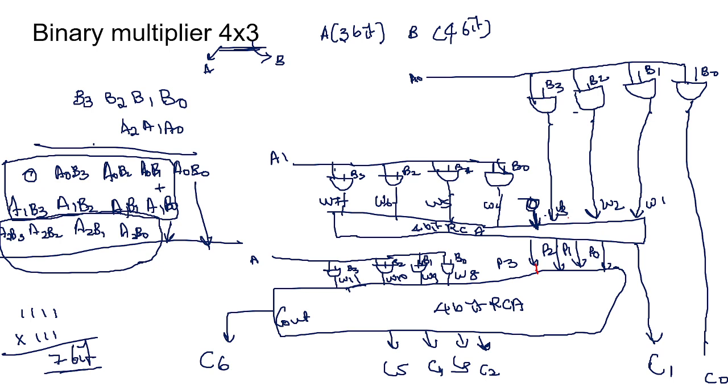So all this W will be wires, and the AND gate terms, the product terms, I am mentioning with W variables, and while defining, I will declare this also as wires. And this is the final output. A0, A1, A2 will be inputs, and B0, B1 will be inputs. So we will have W1 to W11 and P0 to P3 as wires.